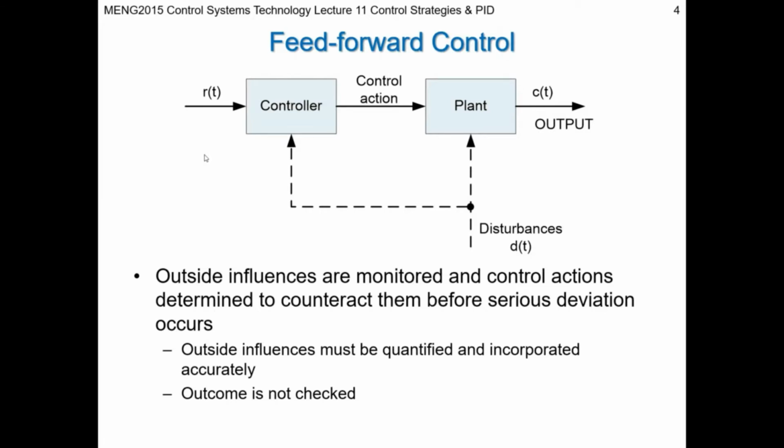But what you can have is a feed forward control system with what's called feedback trim. So you could actually combine both. And of course, if I had my little sketch pad, I would now draw on a feedback loop here. So you can have a combination of both feed forward and feedback.